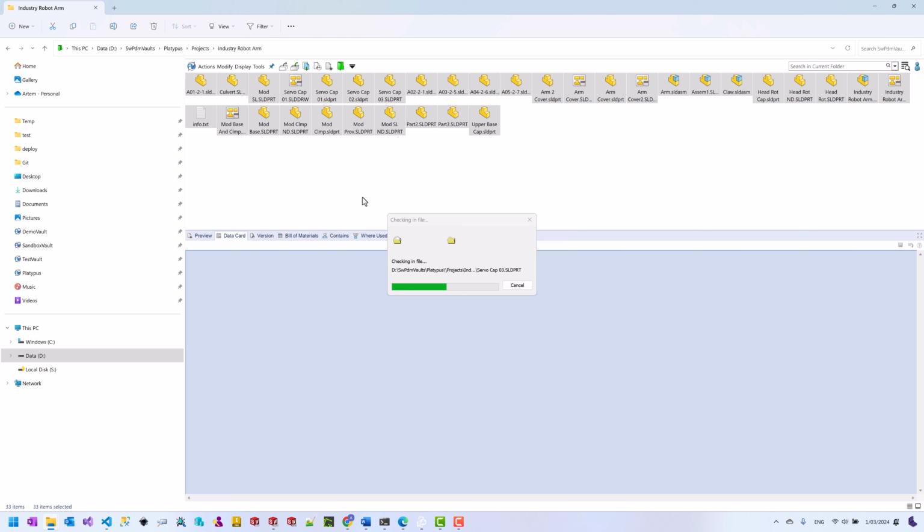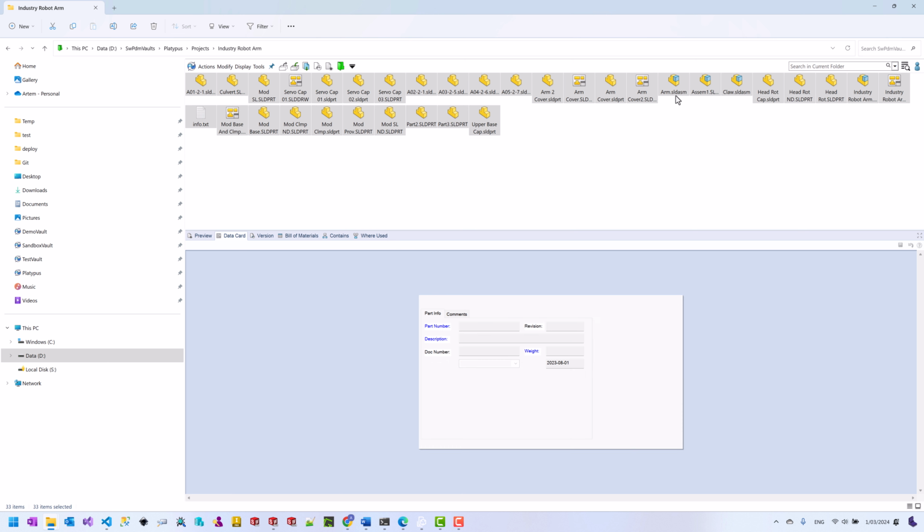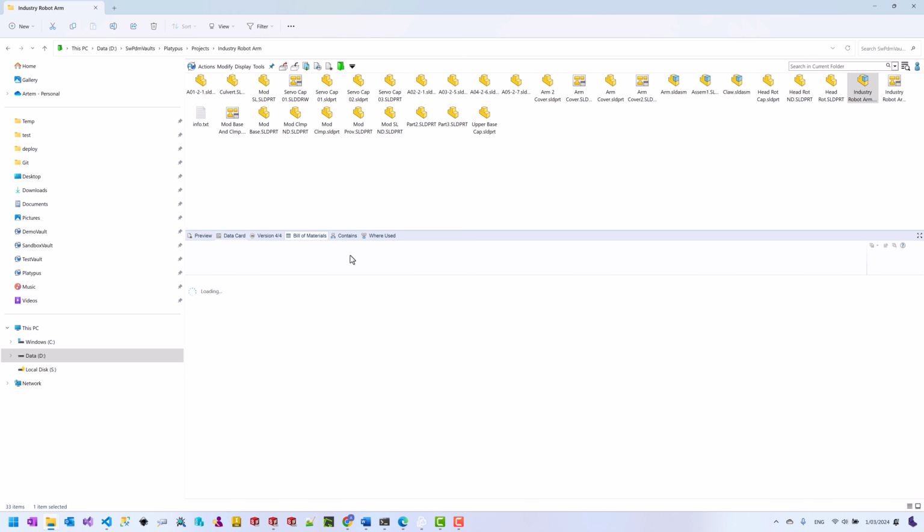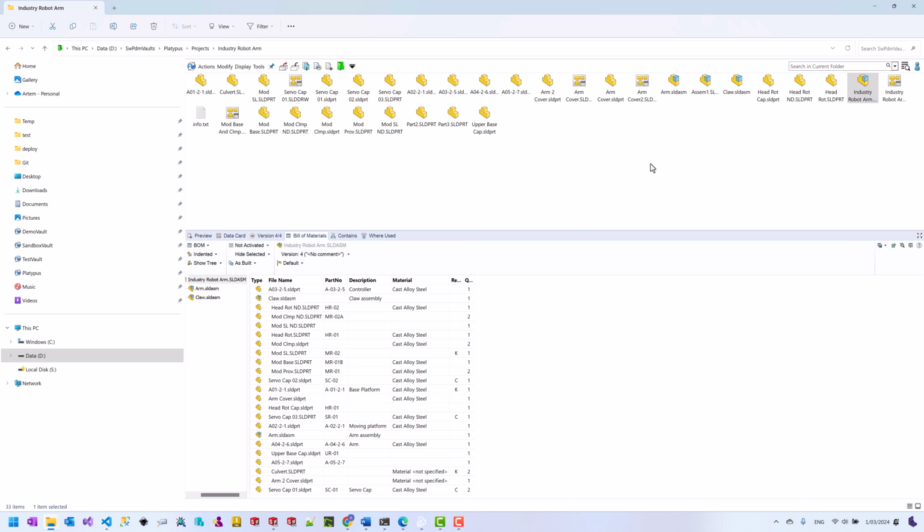It is also possible to access the bill of materials information via BOM Plus here. So let's say if I want to export the hardware components from this assembly, hardware components were designed using the BOM Plus items, so they're not exposed to the bill of materials in the PDM Vault, to the automatic bill of materials. So if I would select my assembly over here, you will see there is no bill of materials, there is no information about the hardware components here, because these are not native files.